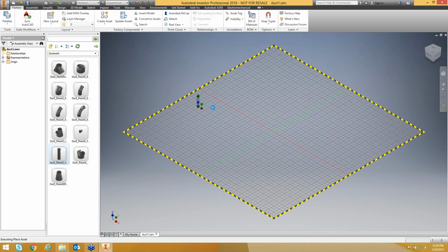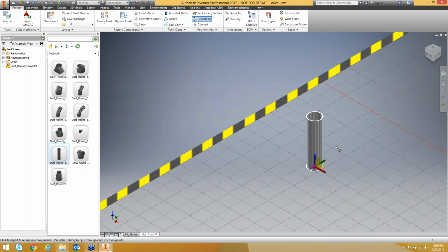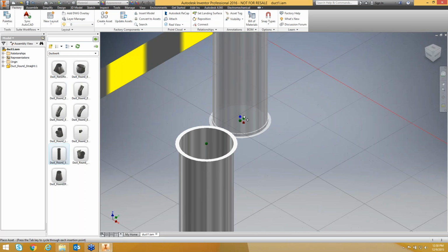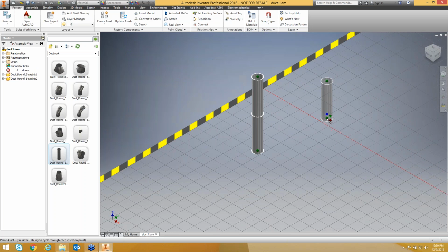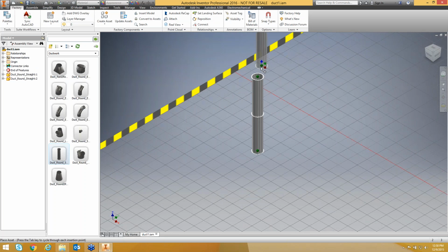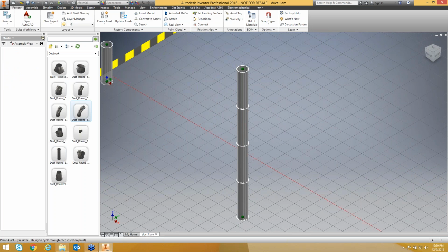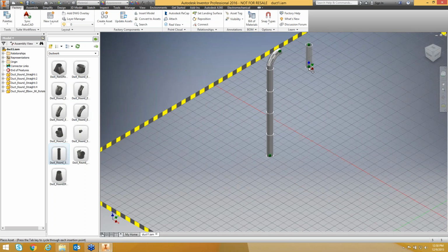And so in this case, if I grab my vertical rising duct and just place it, and the main thing here I'm going to talk about, I'm going to say done. You'll notice the connectors, these green dots. As you get close, it'll say, hey, I like that point. So it becomes like a snap point. As you go, it makes it quick to build it. And then we can come over here and grab an elbow real quick and easy as well, and then go back to our straight piece and add it on there.